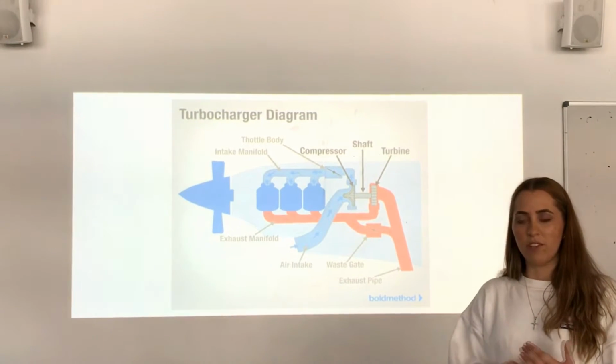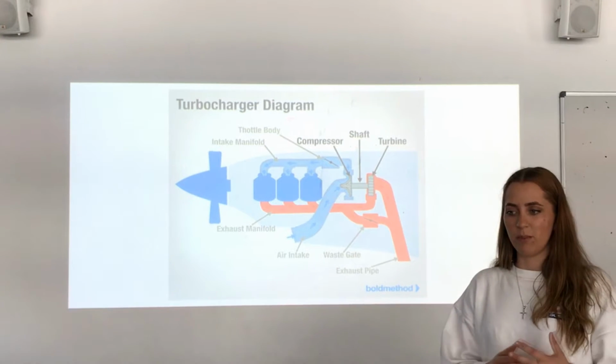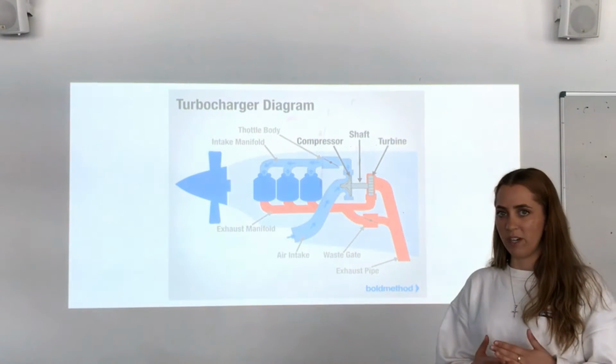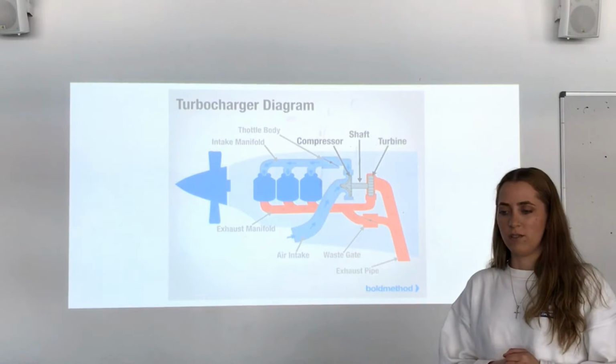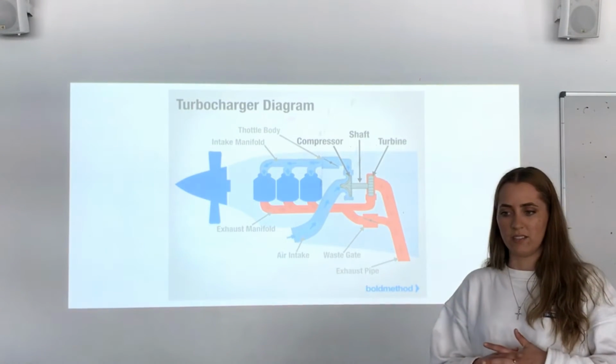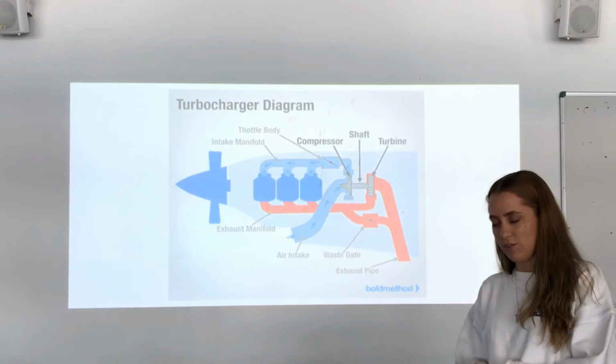An advantage of the turbocharged engine is that the compressor doesn't do anything until the throttle butterfly is actually wide open, and that's when the wastegate can be closed to direct the exhaust gas through the turbine to drive the impeller.